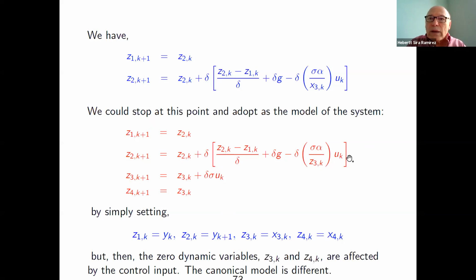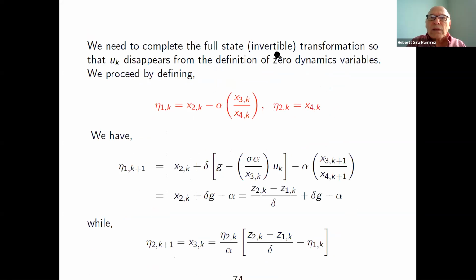The only thing is that when you use some control here to regulate the linearizable part, in order to study the stability of this system, you have to replace the very same control in this equation. And therefore, the analysis is a little bit more complicated, but it's not something that represents a real obstacle.